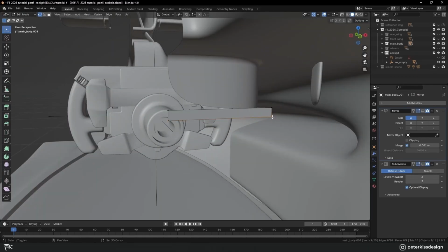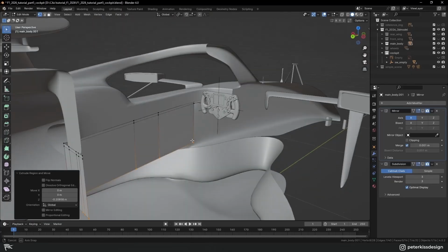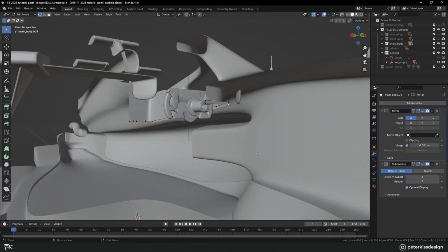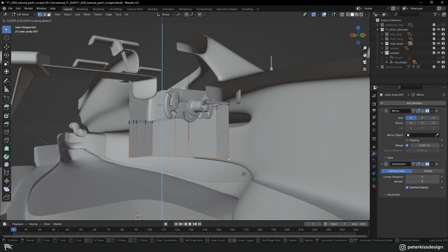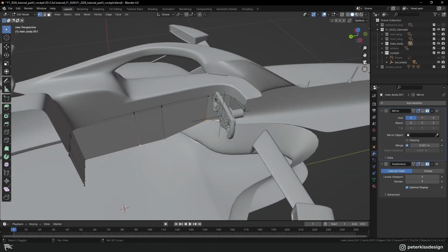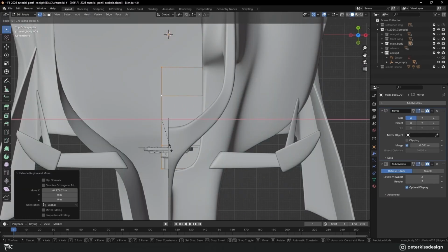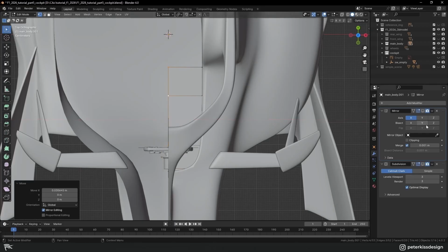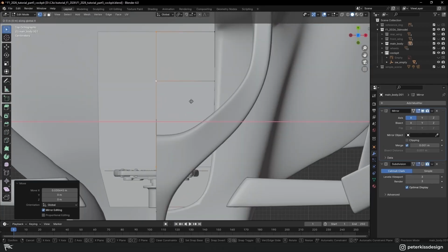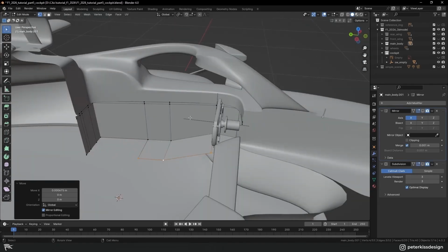Disable the subdivision. Then unselect this one vertex and extrude it down. You can move these two up. Then select these four, go to top view and extrude in X. Scale in X to 0 and move it the way that it connects on the mirror. Now we need to add 3 loop cuts to connect these.